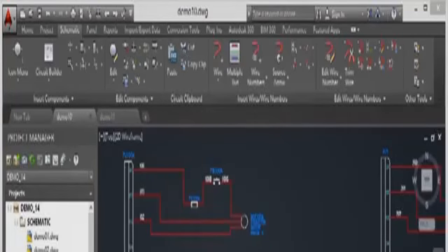Wire numbering. It's got one or more fixed wire numbers found. Keep the fixed wire numbers or blank them all. Do you want to keep fixed wire numbers? That will make them copies. So I'm going to blank them all in this case. I click on OK. Takes a few seconds, and look, can you see everything is blanked out so that I can retag it manually or do a project-wide retag maybe later on. So that's how I can copy a circuit in my AutoCAD Electrical drawings.